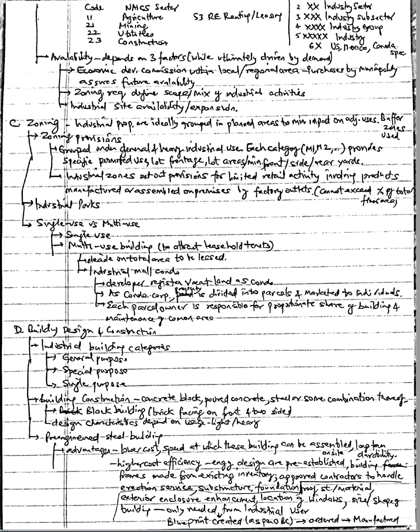The office area is typically 15 to 20% of the total industrial area and it's either contained within the building along with a mezzanine level above the standard height office ceiling, or extends out from the primary structure, sometimes referred to as a box on box design.